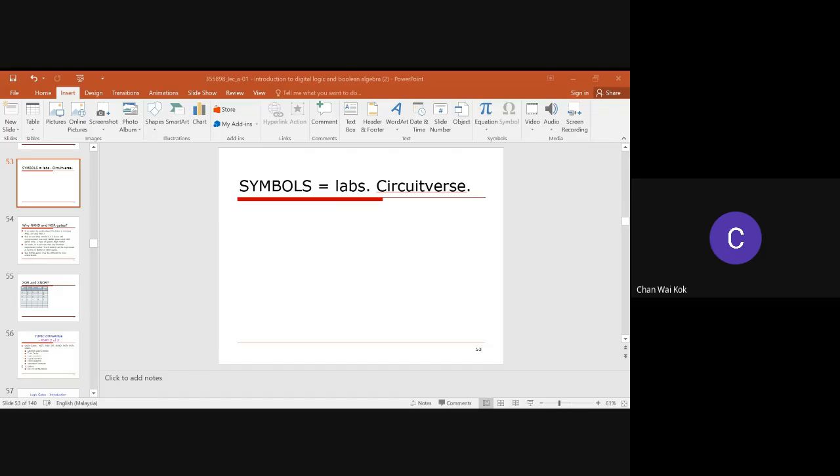Every function is expressed in NAND gate only. So in your chip, NAND gates only. Here, only one type of gates, NAND gates only. So you can build as many as you want. Connect how you want to connect them, up to you. But just NAND gates only. Okay, so it's much easier. Not necessarily reduce the size of the circuit. It makes things easier.